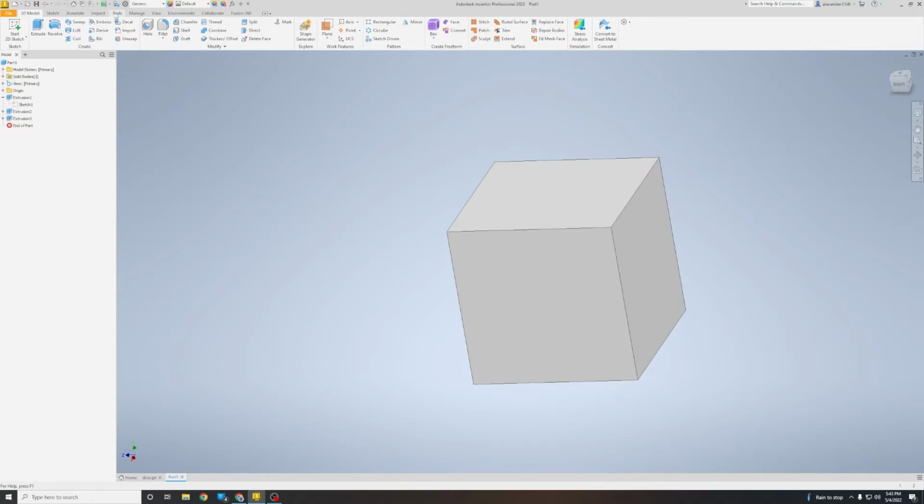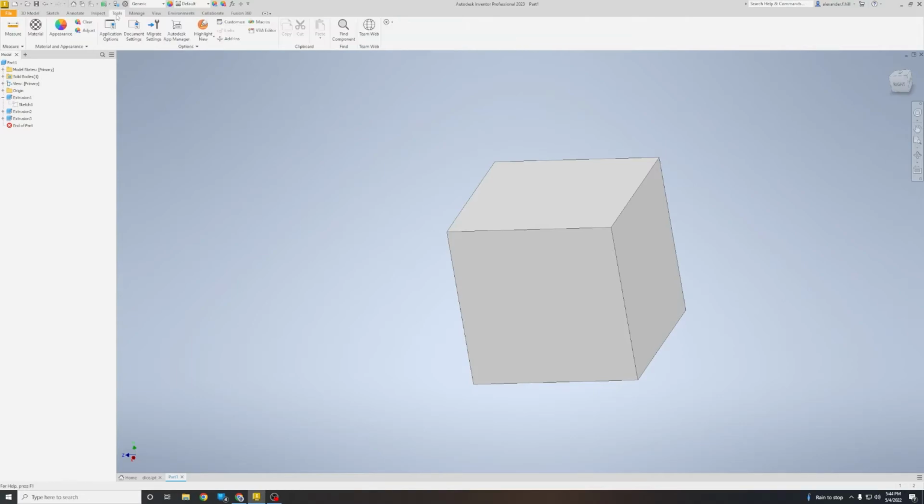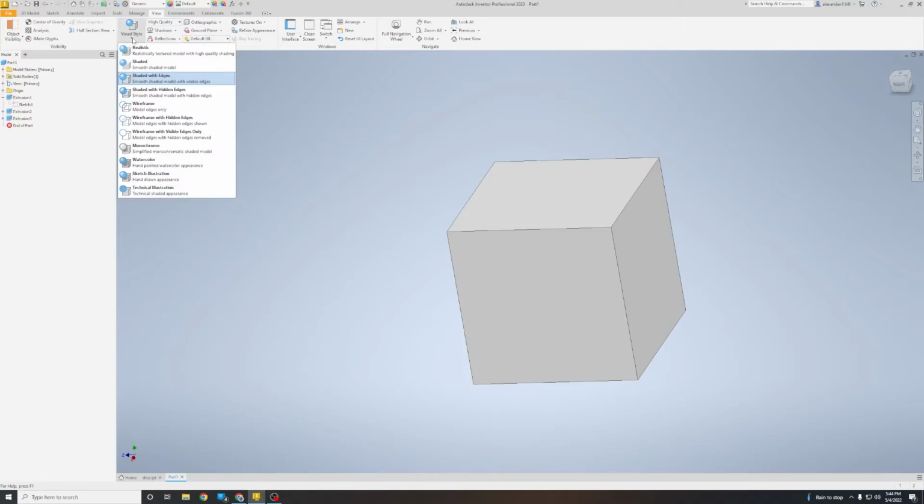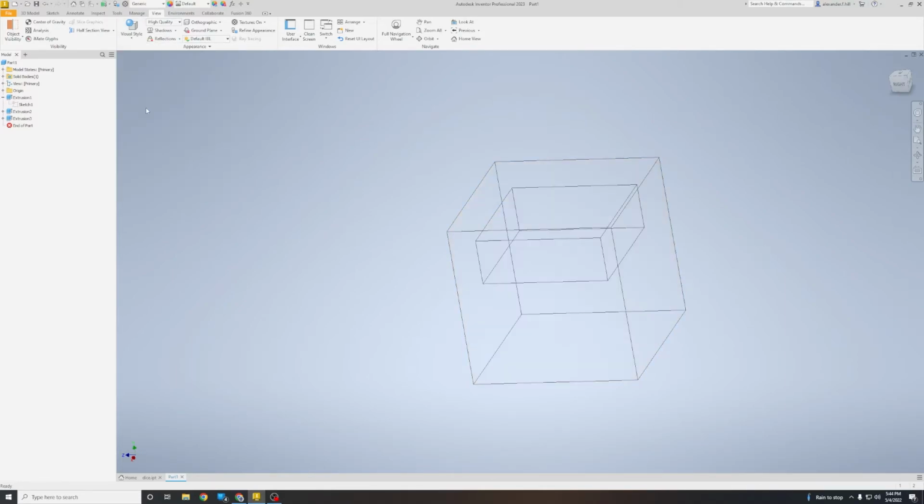Let's take a look. Using the Tools tab, and then actually clicking the View tab, I can click the Visual Style. This brings a drop-down menu where I can select Wireframe. And I can now see inside and through my model. I'm only seeing the edges. This confirms to me that yes, indeed, there is a secret light hollow spot inside that will help my dice land.